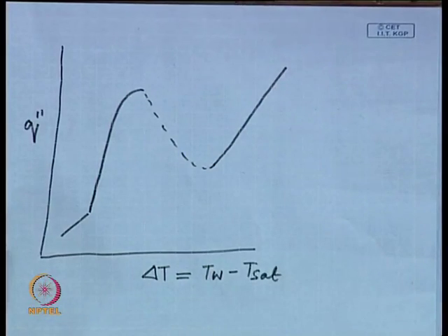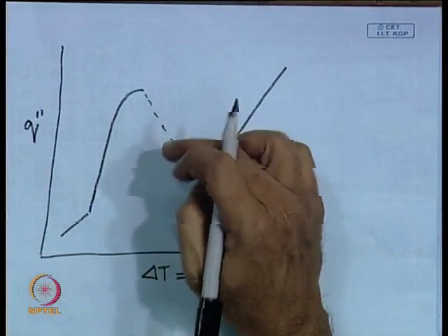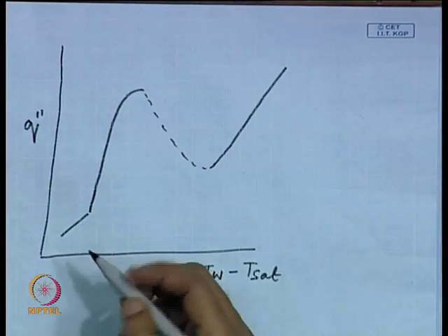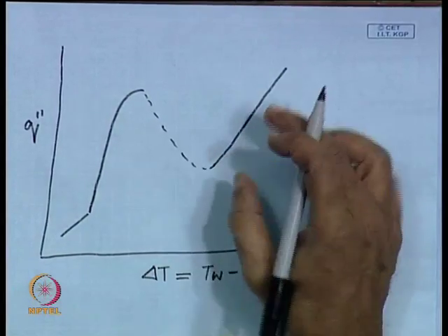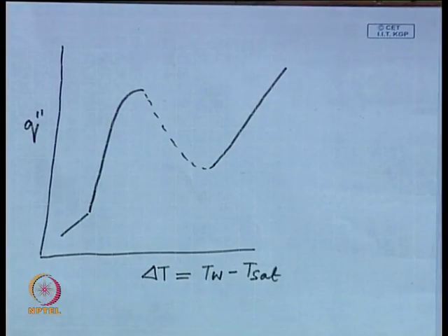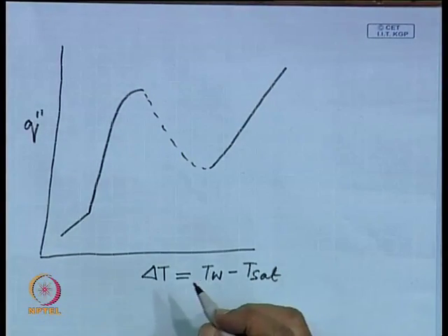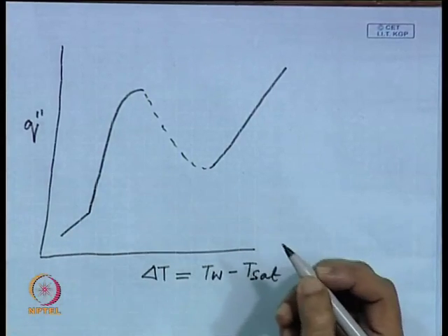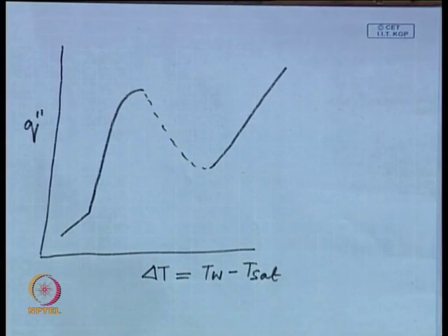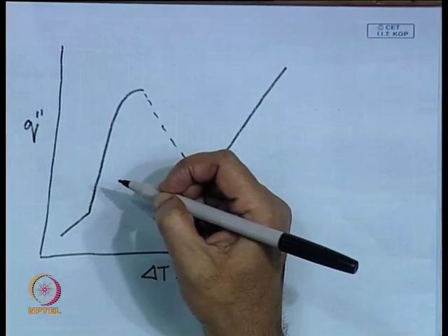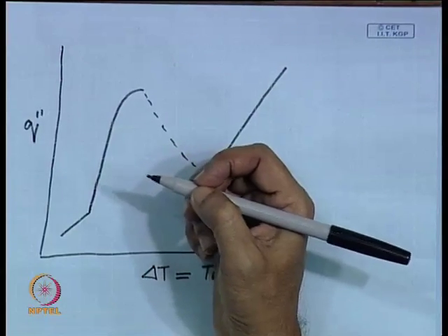In a heat flux controlled experiment, we will get only the portions shown by the firm line. That means we will get the nucleate boiling and the film boiling region. Transition boiling we may not be that successful in getting. In the nucleate boiling and film boiling regions, there are again different regimes of boiling which do not follow the same laws or the same mechanism of heat transfer.